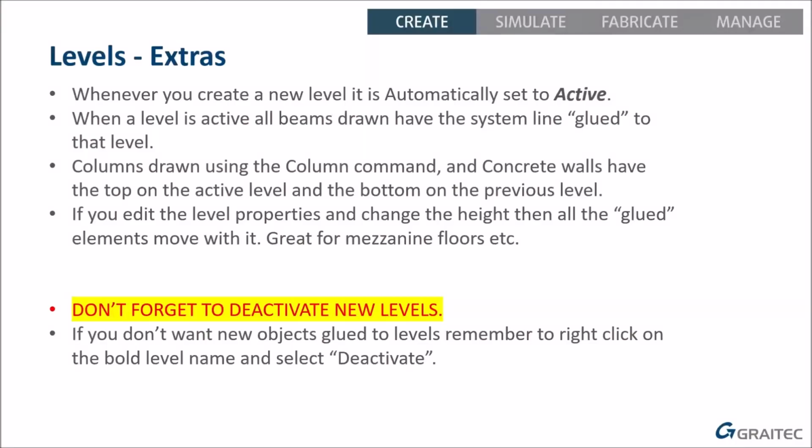So really important, don't forget to deactivate new levels when you create them, but when you want them active, or you want new things to go locking onto it, you can right click and say activate again to go back and draw more things glued to that level.